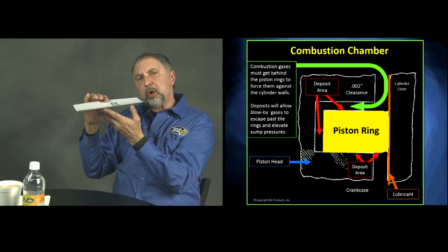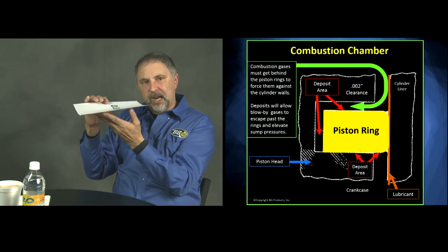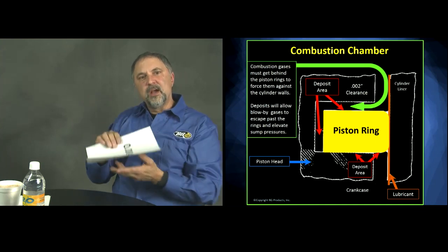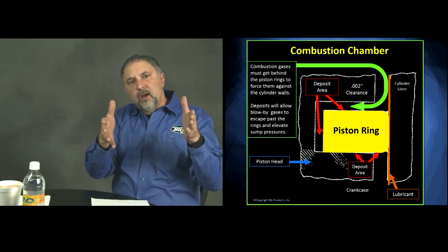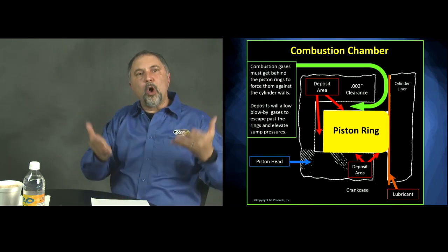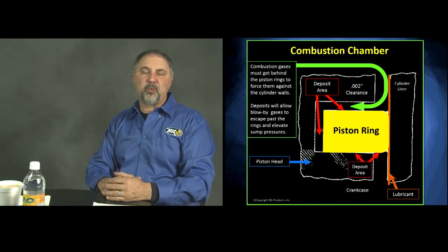So if you can envision in your mind's eye deposits that are accumulating inside that combustion chamber and being pushed into the EGR valve, if it gets stuck in these rings, you're going to have these rings allowing blow-by gases down in the sump, fuel down in the sump, and oil back into the combustion chamber. So it's imperative we keep these rings clean.